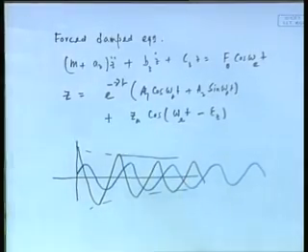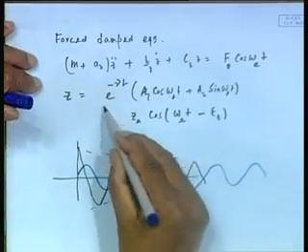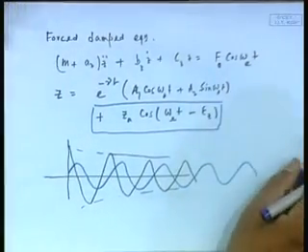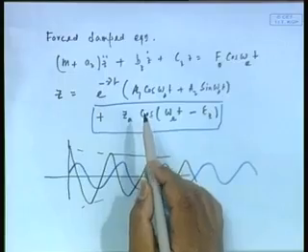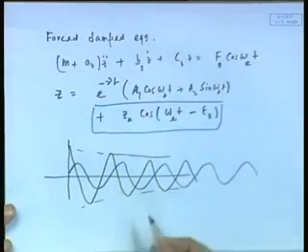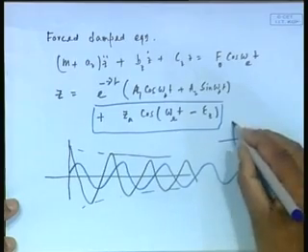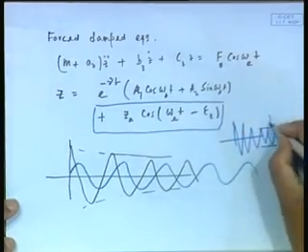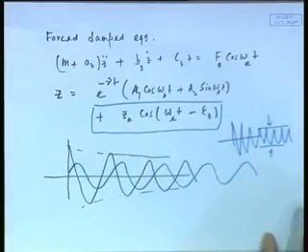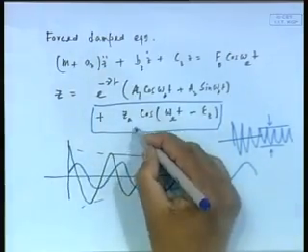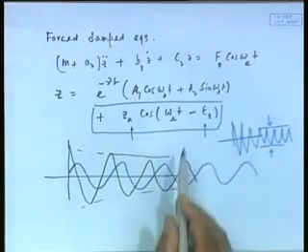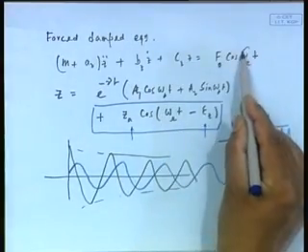Now, the question is what is our interest? Our interest is obviously only in this part. Why? Because given sufficient time, this thing will decay because of the nu factor. So, essentially if I am looking at a steady state solution, that means if I am holding for a long time, what would happen? The body will begin to heave only with this forced oscillation, because this one will decay down. In fact, the full solution, if you were to draw it from an experiment, may look something like that, and ultimately it will become a straight line. So, this is what I am looking at, this is my full interest. So, we are looking at only the steady part of the solution. Again, here my unknowns are this and this, and what you notice here is that this is oscillating at the exciting frequency omega e.